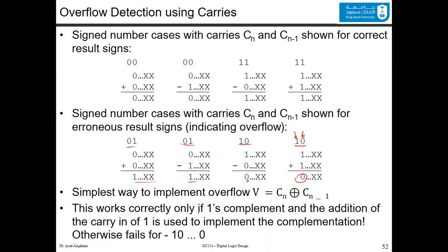This works correctly only if the ones complement and the addition of the carry n of 1 is used to implement the complementation. Otherwise, it has some issues. So if you do the subtraction this way, this overflow detection would be correct.